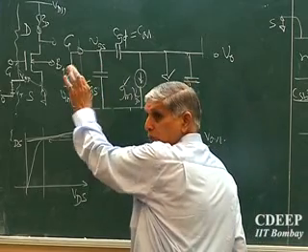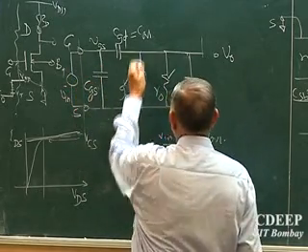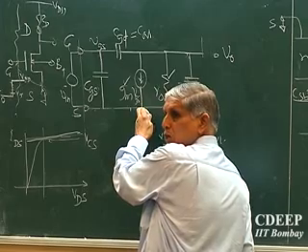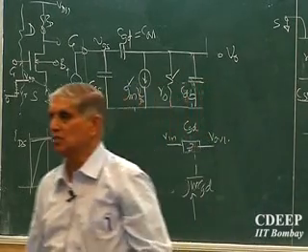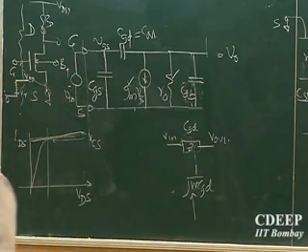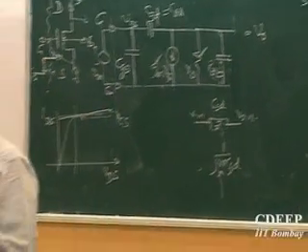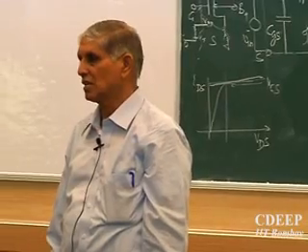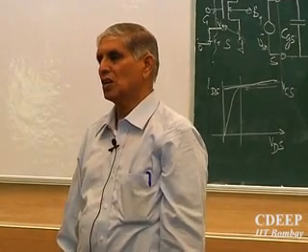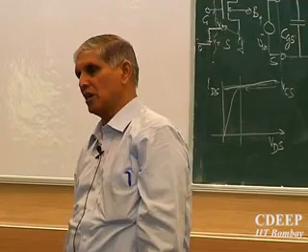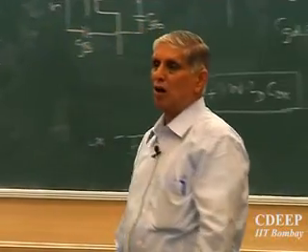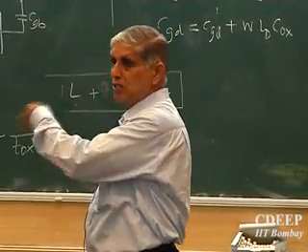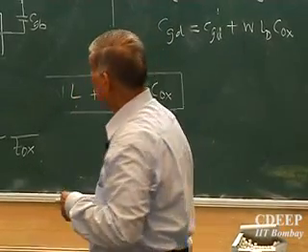Gate to source open circuit, VGS, correspondingly the current source at the output is GMVGS, across it is the resistance, which is the output resistance of the transistor R0, and therefore you can always evaluate the gains. Is that correct? Always evaluate the gains using the MOS amplifier. This is how we actually perform all analog designs. Okay. Next semester, more details.